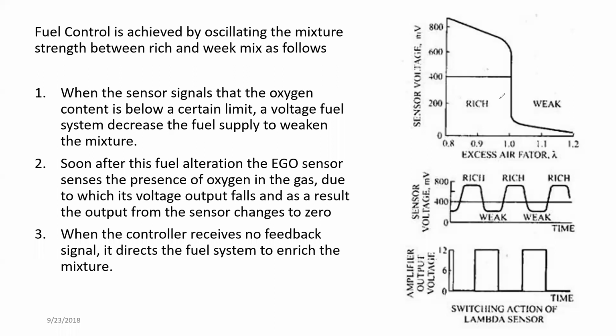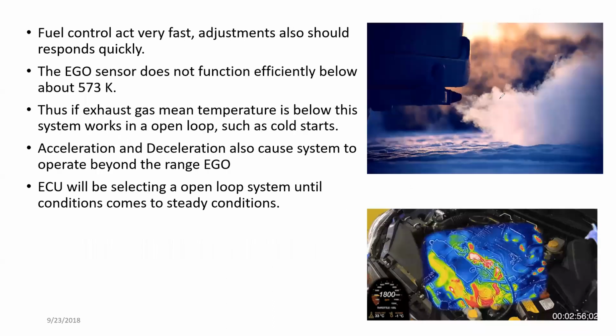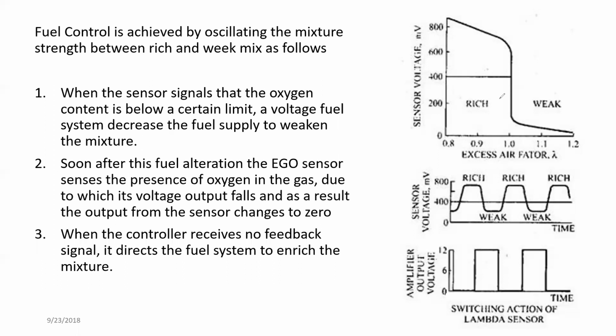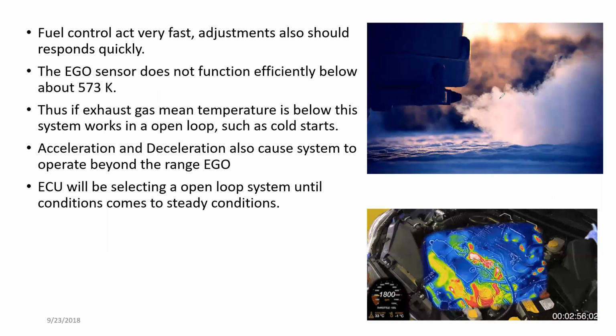But while this is going on, when the air fuel ratio is changing, as we discussed earlier, the ignition also has to be changed. So while the fuel system is working on this, the ignition system is working on maintaining the ignition timing at a sustainable level, so the engine will not create a knocking.